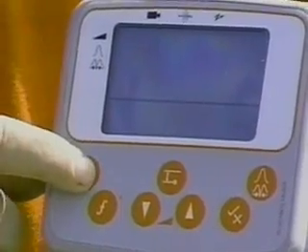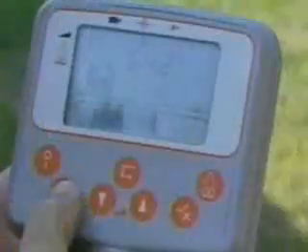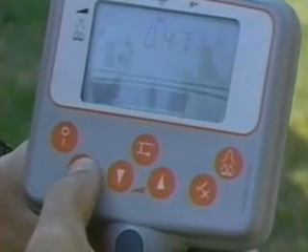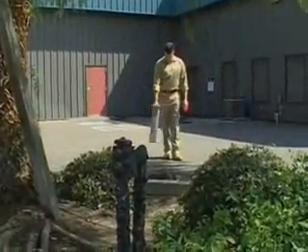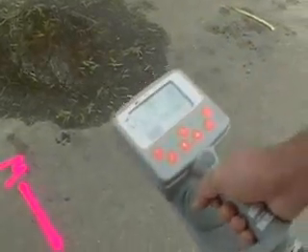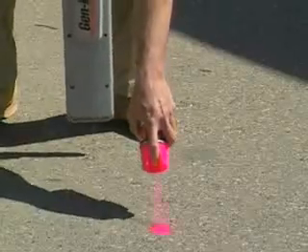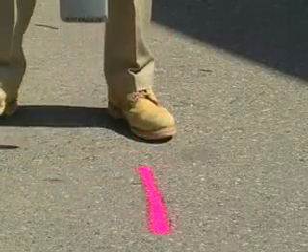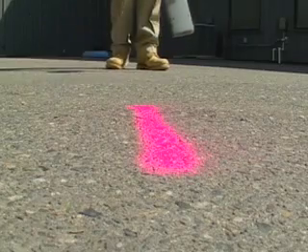Turn on the locator and set the frequency to pipe location mode. Make sure the blade is perpendicular to the ground and across the pipe rather than in line. Move the locator side to side and look for the maximum signal. Mark the pipe location. Continue locating, marking pipe location every 3 to 5 feet within the leak survey area.